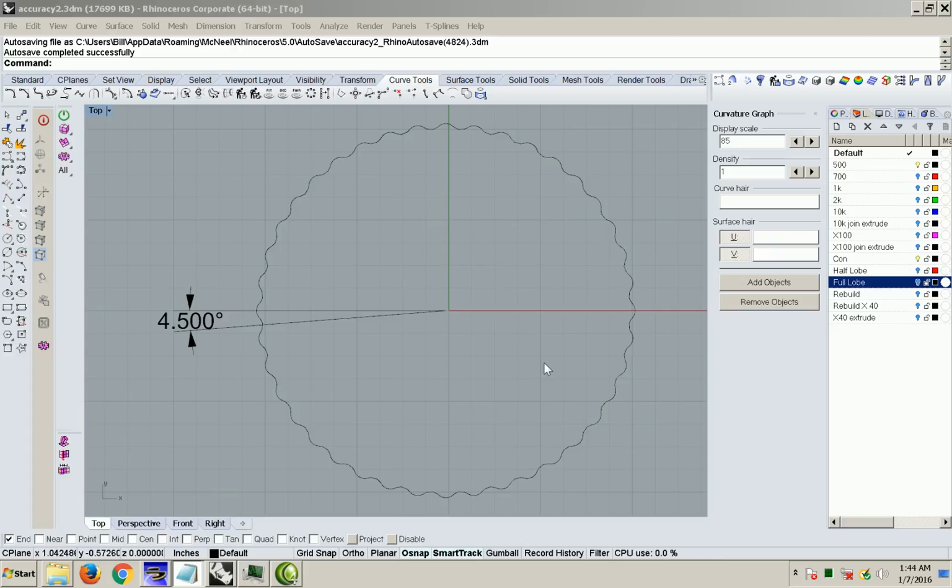Whenever you see a step, it indicates that the segments of the curve are not tangent, or not a smooth transition between one another. One way you can fix this is to convert the polycurve into a NURBS curve. In reality, this lack of tangency causes a very small amount of error, but since I needed to convert it for the purpose of consolidating surfaces, I figured a small increase in accuracy was an acceptable byproduct.